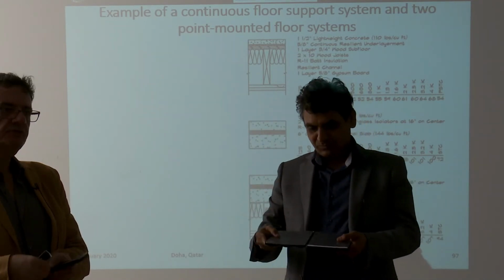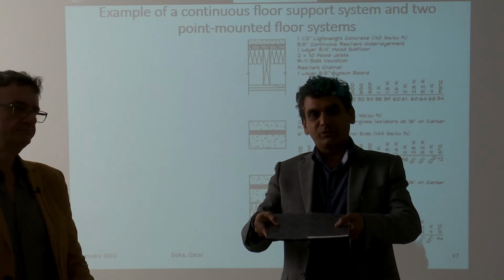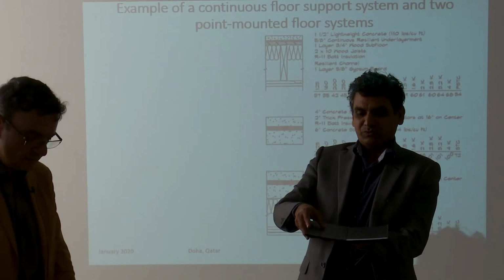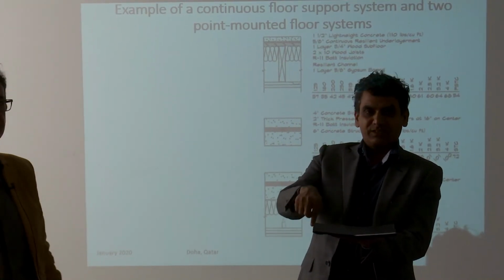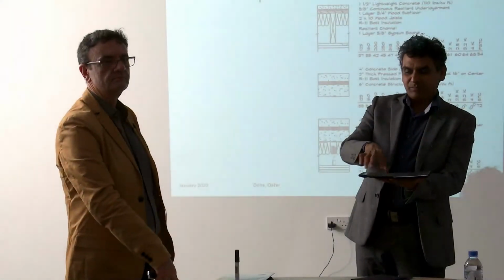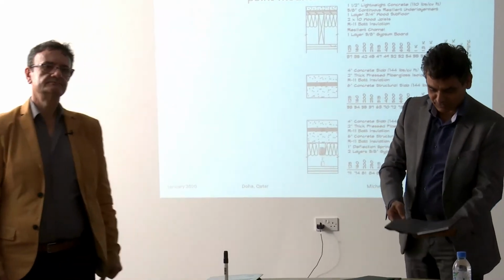So you must make sure that your installation, all the joints, are taped properly, and not let the concrete flow over the edges. His point is that on top of that there is a plastic coating and a tape, so it will not allow the wet to go down. Your question is right.